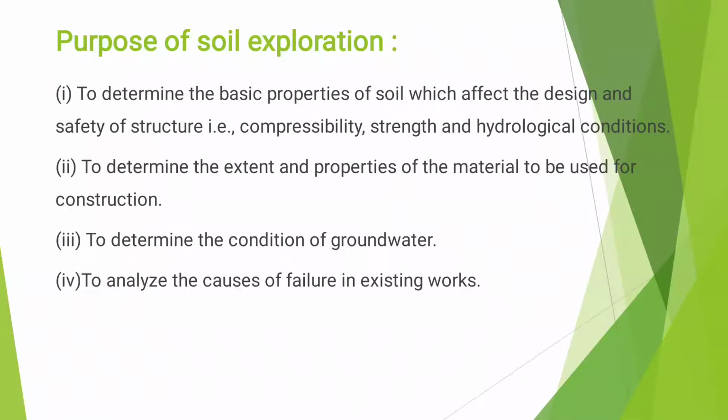Next one is the purpose of soil exploration. Why is it needed? For determining the basic properties of soil such as compressibility, strength, etc. Next, to determine the extent and properties of materials which are used for construction. Next, determining the condition of groundwater, and to analyze the causes of failure in existing work.